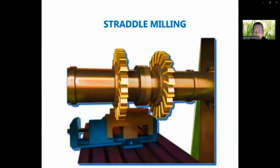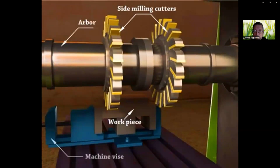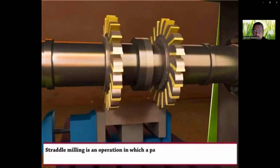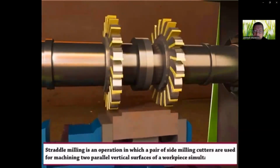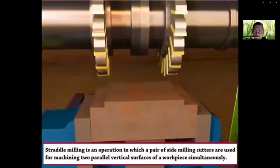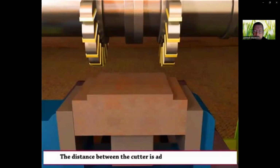Straddle milling. Workpiece, side milling cutters, arbor, machine vise. Straddle milling is an operation in which a pair of side milling cutters is used for machining two parallel vertical surfaces of a workpiece simultaneously. The distance between the cutters is adjusted by spacers.